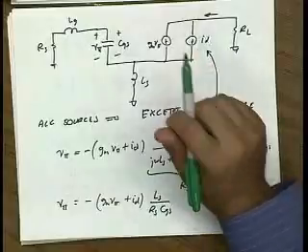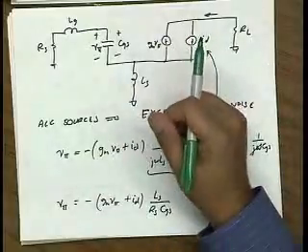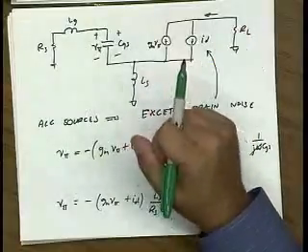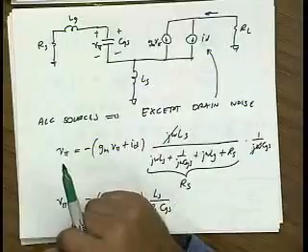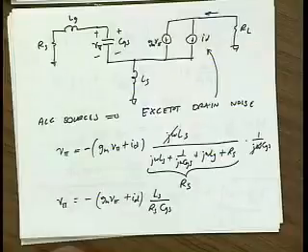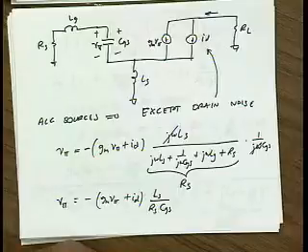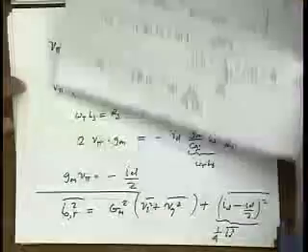But for all practical purposes, at say ft over 10, ft over 5, the phase shift is very small. But it's actually a great question, and we'll see this actually happening when we look at a cascode device. That phase shift is important. I'll hold off on that comment until we look at the cascode device.